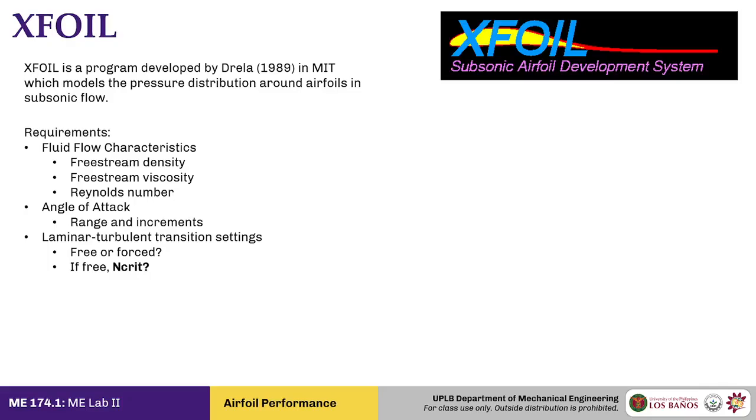Ncrit, I think, is unique to Xfoil, I'm not sure, but this basically describes how unruly or how unideal, or basically how rough the velocity profile of your wind is. Usually this is left at the default of 9, because that ncrit value is matched with an average quality wind tunnel.